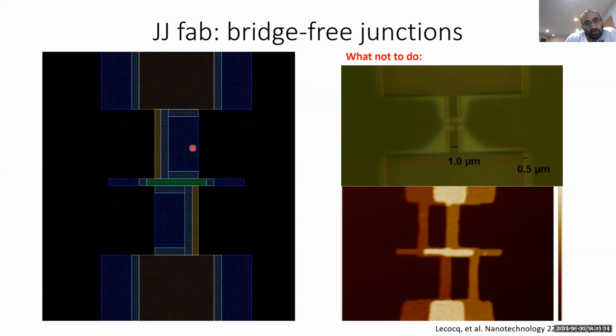The dark blue is going to be a low enough dose to expose the MMA without exposing the PMMA. But in the light blue, because this light blue region is adjacent to the brown and the yellow region and the green region, which are all exposed with high doses, there's going to be some proximity effect. And so as a result, the additional exposure that's needed during the writing of these light blue regions needs to be slightly smaller.